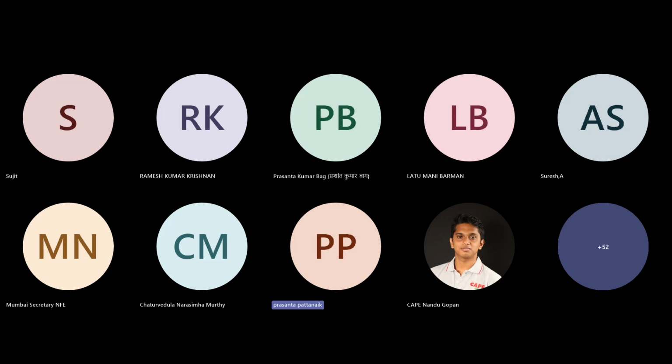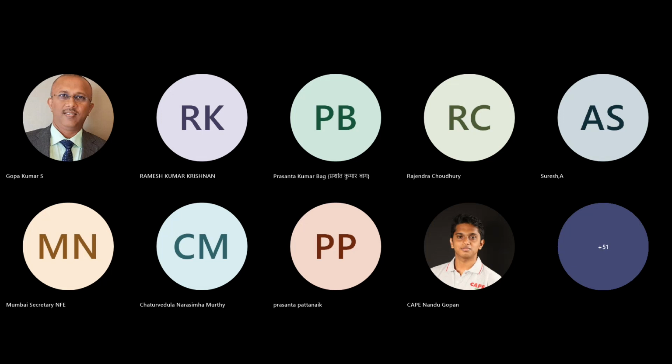And the way Gopakumar sir explained, it is really a fantastic way he explained the T and N systems, TT and TN systems and all. But the question is that for equipment earthing, you have to understand that it concerns the metallic non-current-carrying conductive parts. If you are attempting to earth them, that is called equipment earthing. As you are finding, the body of a metallic enclosure being earthed is called equipment earthing.